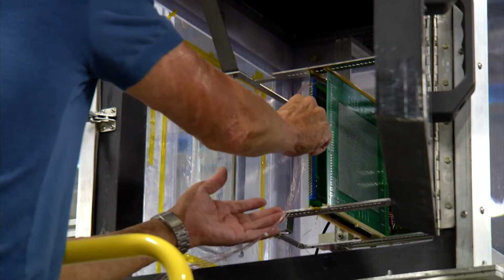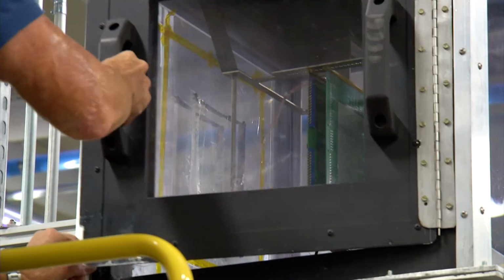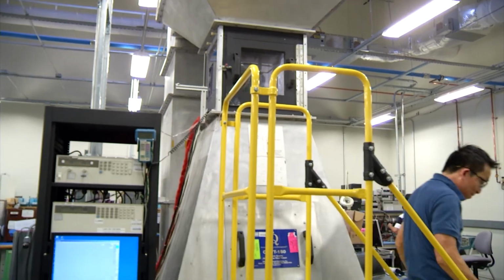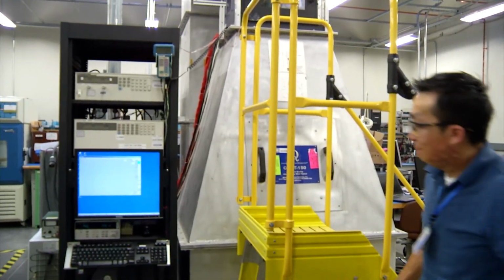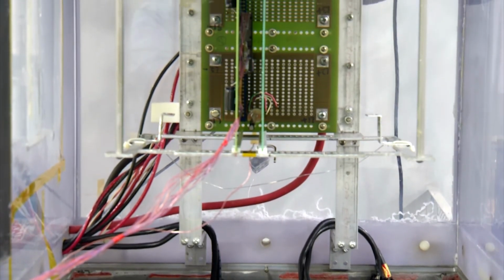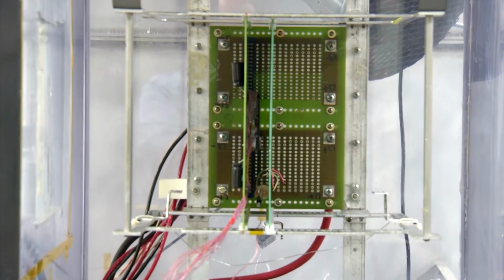The converter is soldered to a test board, which simulates the customer's circuit board. This test board is then mounted into the wind tunnel, and an offset test board is placed opposite the module to create a channel through which the controlled airflow will pass over the module. An anemometer used to measure the airflow and an ambient thermocouple are placed 3 inches below the module to measure the input airflow and temperature. The testing is then started.